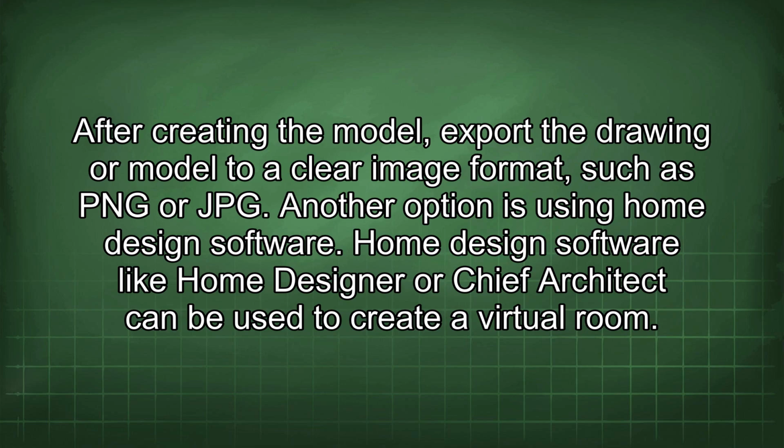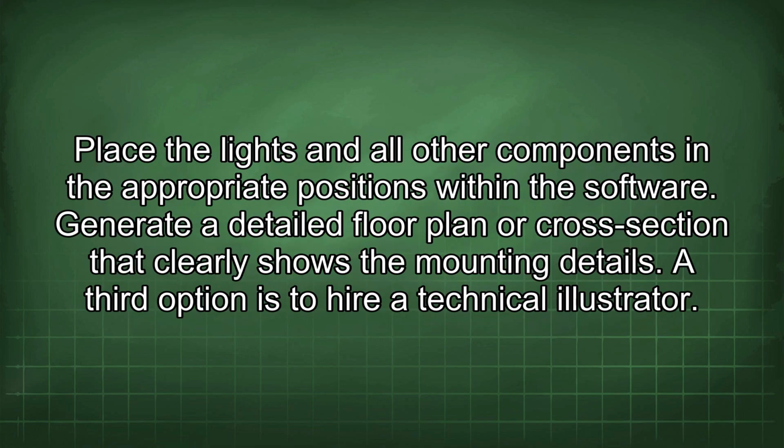Another option is using home design software. Home design software like Home Designer or Chief Architect can be used to create a virtual room. Place the lights and all other components in the appropriate positions within the software. Generate a detailed floor plan or cross-section that clearly shows the mounting details.